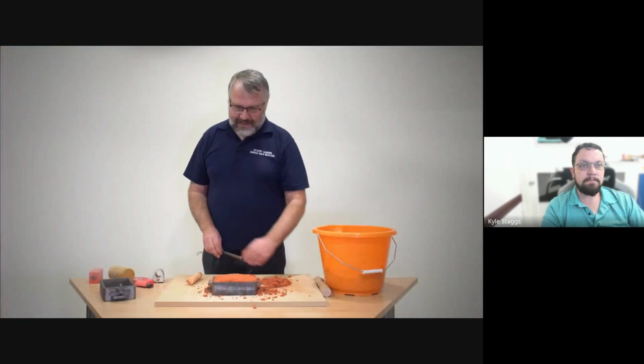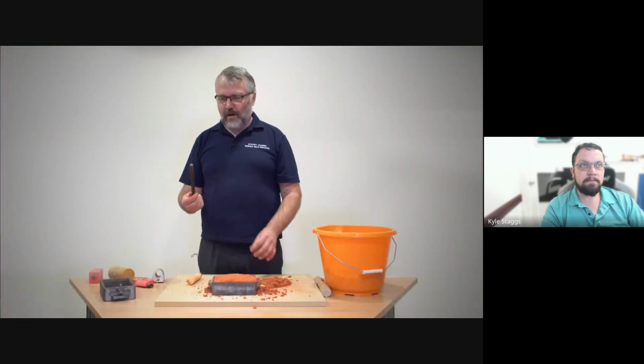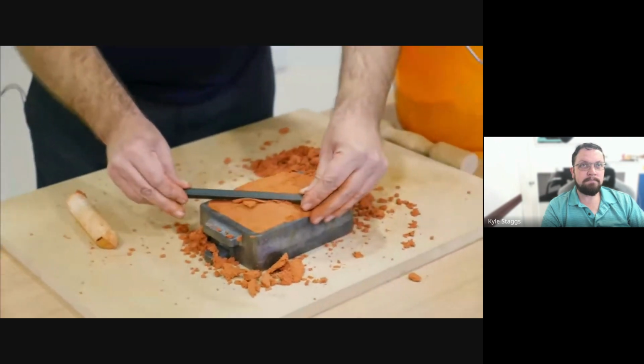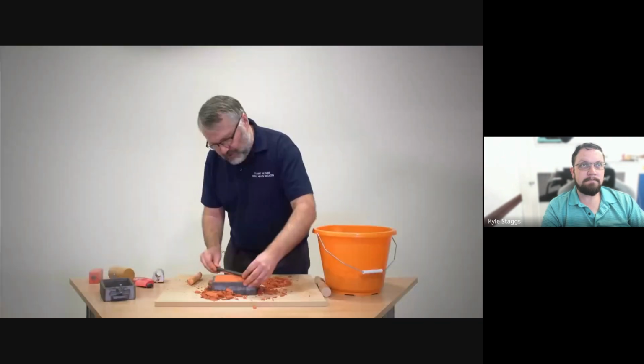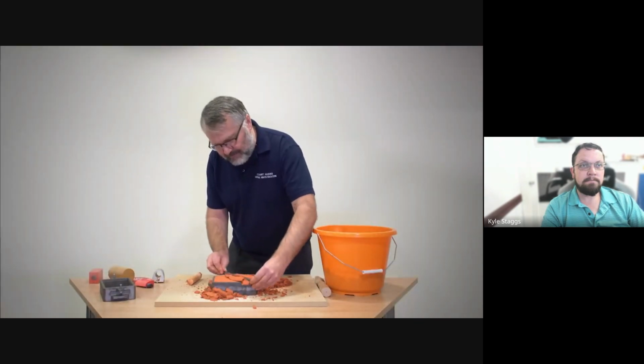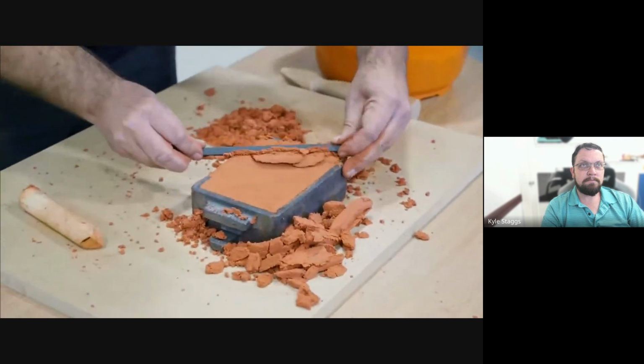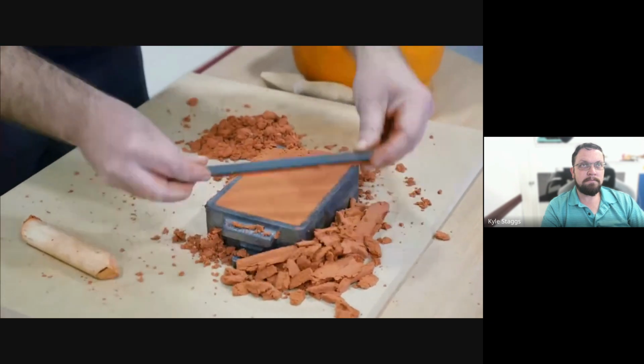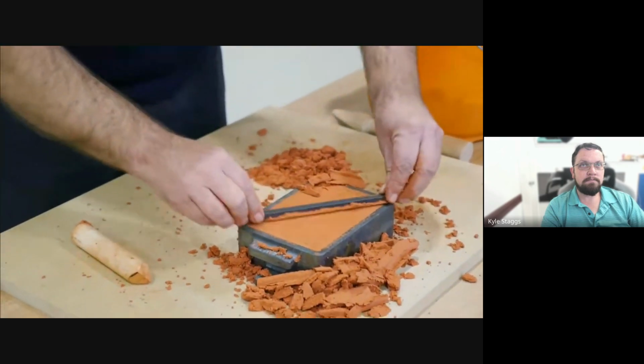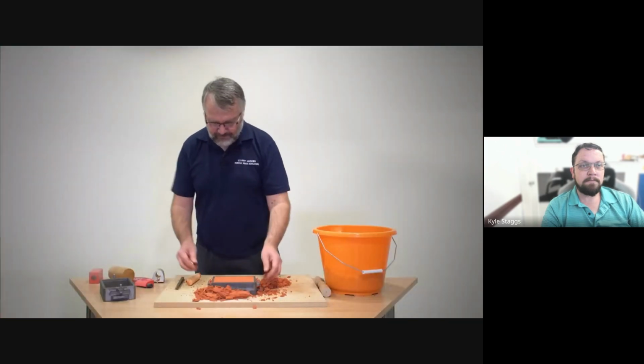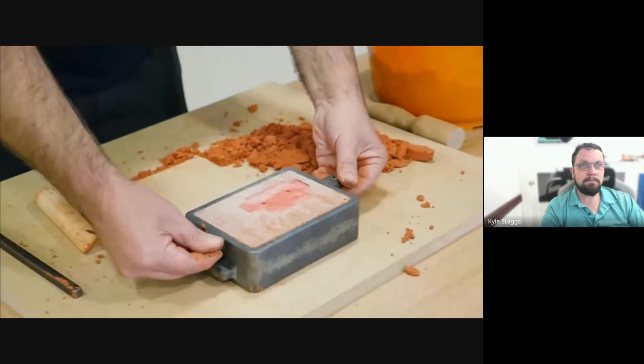We now need to level off the sand, and that's just done with a piece of bar. The process is traditionally known as strickling, so the tool we use is known as a strickling bar. And if we use a sawing action and take it off a piece at a time, we end up with a nice, flat, firm surface. And turn things back over.